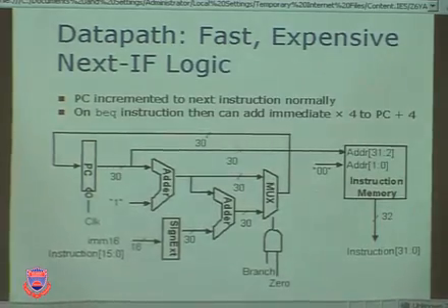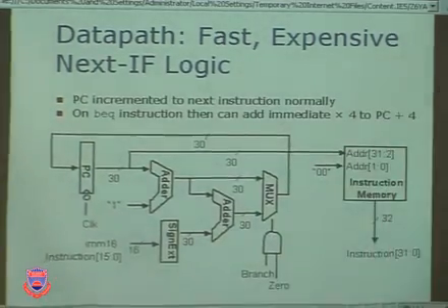Now the last little bit is, let's look back this way and figure out how did we get PC plus 4 plus the immediate sign extended shifted by 2 bits, two zeros. And if you look at that, you'll say, well, it doesn't do that. It takes PC plus 1 plus the sign extended 16-bit immediate. It doesn't do any 4s. There's no multiply by 4. There's no add 4. You're exactly right. And now I'd like to toss the ball back to you and ask you to think, why is it that we're not messing with 4s anymore?